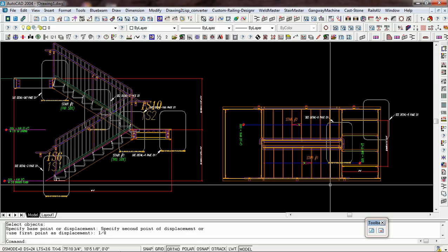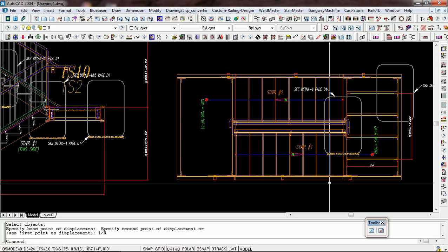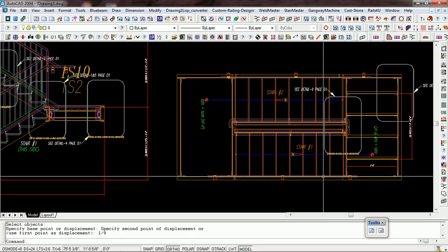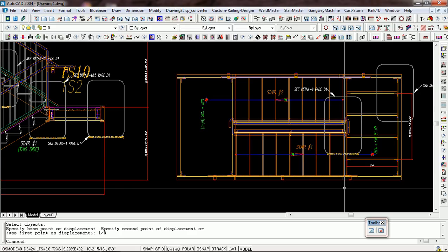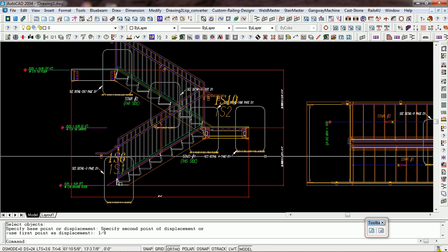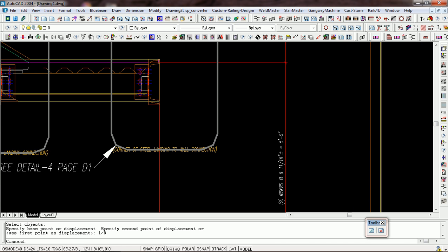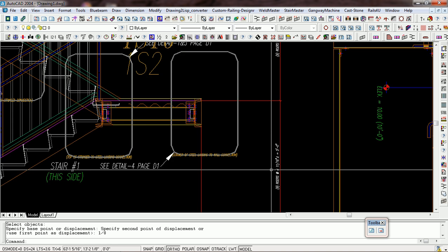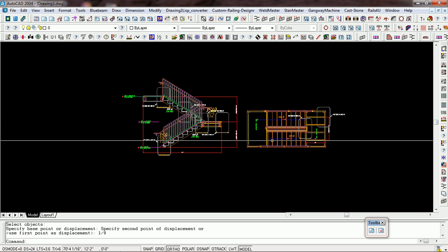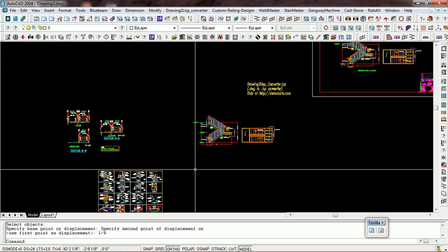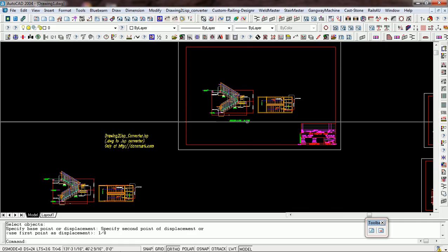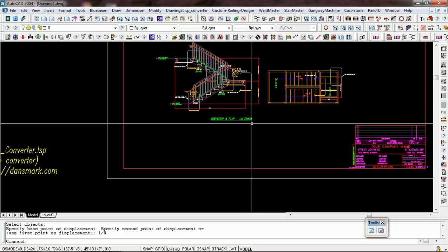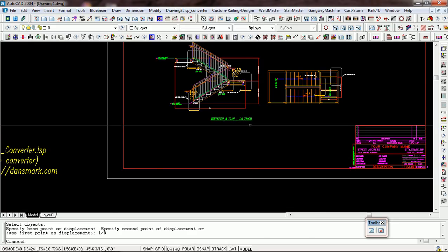And that's completely configurable also in the dialog for StairMaster, what the stair clearance is going to be, whether it's an 1/8 of an inch all the way around, or a 1/4 of an inch, or 3/16, or whatever it is that you want to put in there. So anyway, it also keeps track here. It tells you how many risers and the total for the riser. Same thing over here. And what's really interesting is, it creates this shop drawing right here with the elevation and the plan view. And if you have multiple floors, like in the next video, it keeps track of all those too.